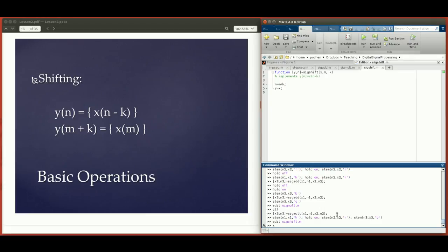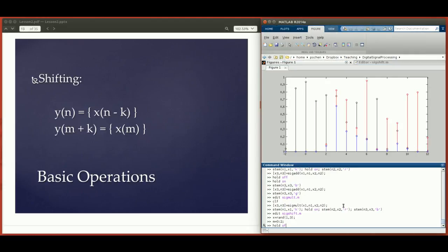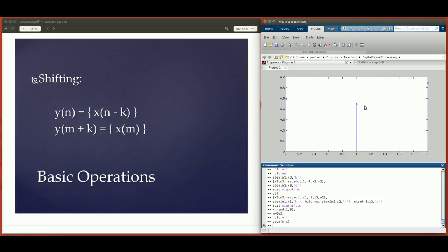We're going to just use x signal that equals a random signal, one row, 3 columns, and m equals 0 to 2. So that's going to be our input signal. Stem mx. So that's our input signal with just 3 sticks. And let's try to put it into the sig shift function. Let's call it yn equals sig shift xm.